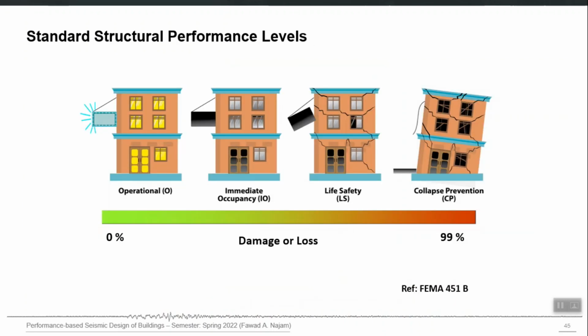So once the structural performance is established as the result of nonlinear analysis, you can convert that performance into any other loss. For example, immediate occupancy can be converted into repair cost, it can be converted into downtime, and there are models available which can convert the analysis results into number of casualties also. If you give all that sophisticated information in the model, how many people are there, what is the type of building, and everything, all that detail, right?